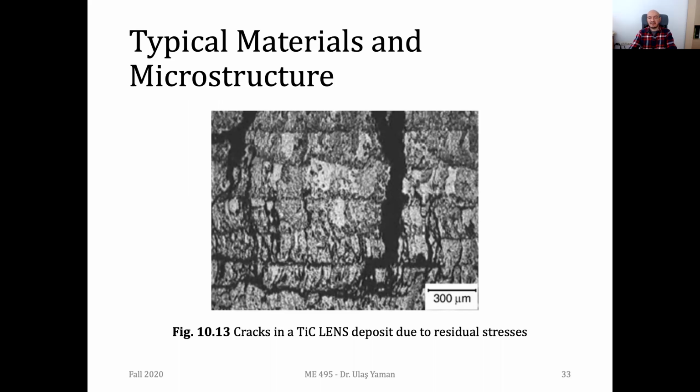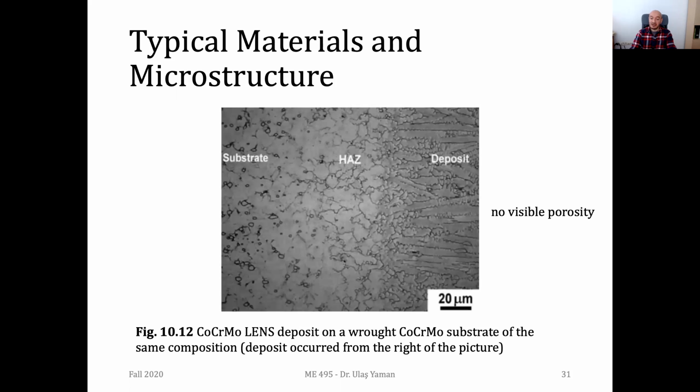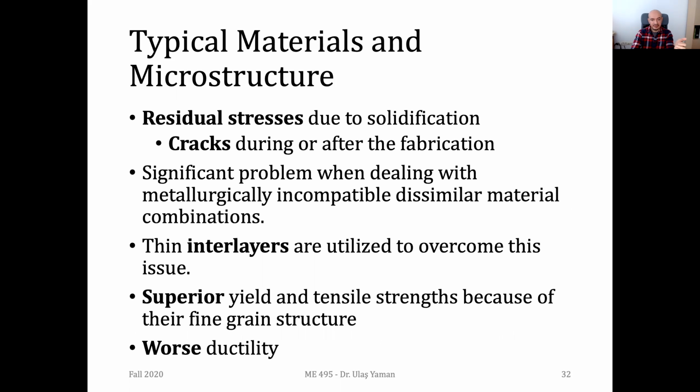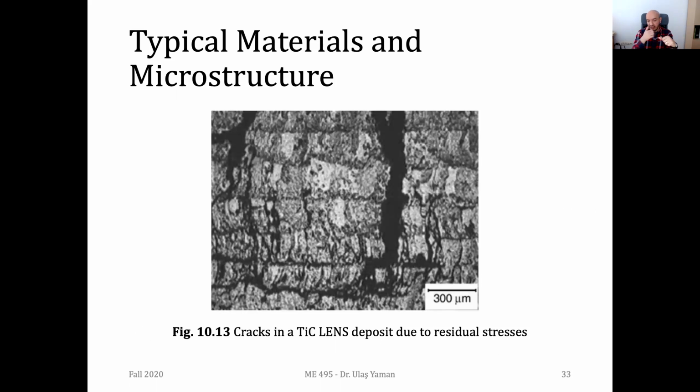These cracks actually happen not with high solidification rates. This is due to probably dissimilar materials, some other missed parameters, let's say. But if you set all the parameters properly and have high solidification rates, then probably you're not going to have any cracks. And these cracks may happen due to, let's say, some gases inside. If your shielding gas, shielding atmosphere is not proper, you may have these cracks also. But it's not highly related with the solidification rates.